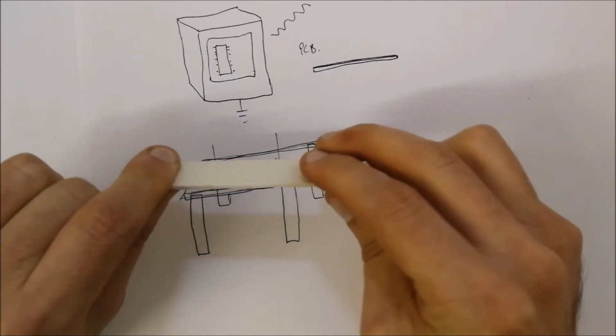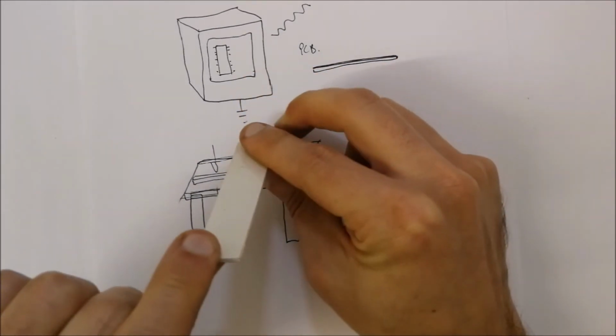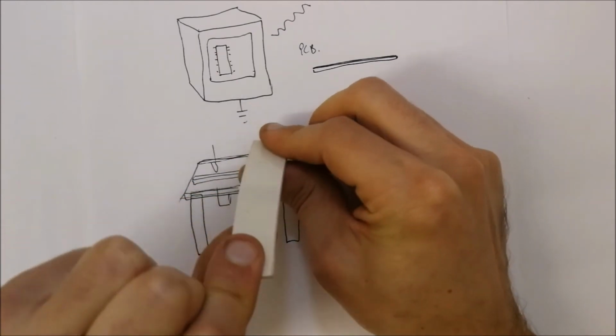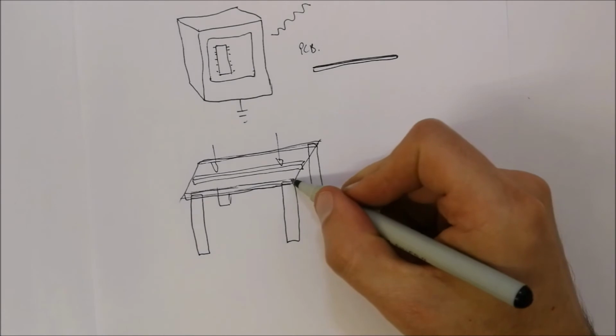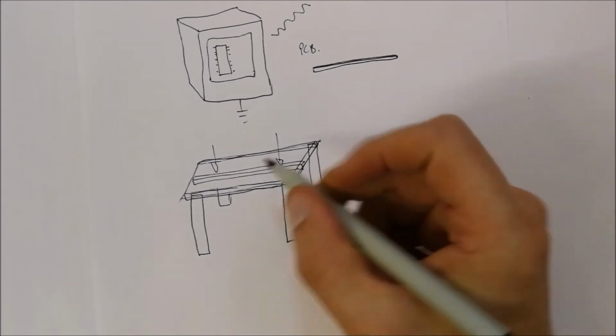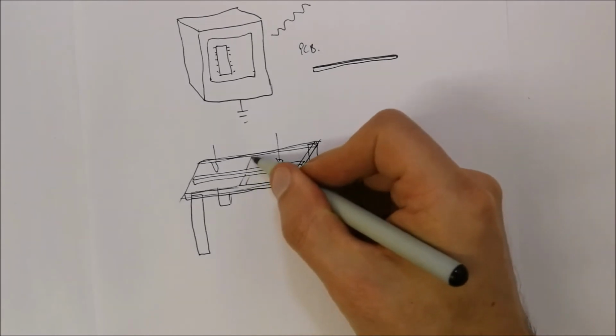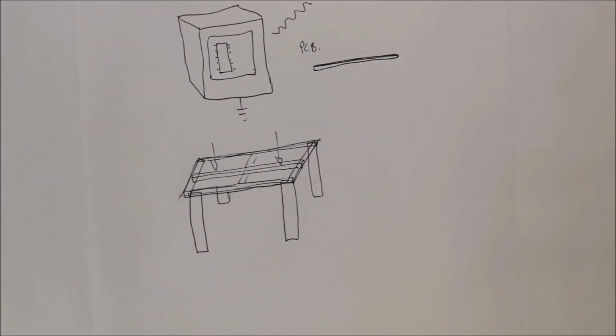But what about the table in this type of formation going into the page? It prevents it from bending that way. So we might also need to have a strip of square tubing or angle iron here on the sides. Maybe over here in the center as well, and over there, just to make it stronger.